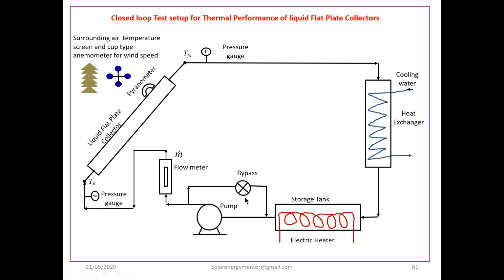Imagine that instead of this bypass valve, a single flow control valve is provided here. In the first case the valve is open and the pump is discharging under a certain pressure. Now the person wants to reduce the discharge, so he will close the valve.